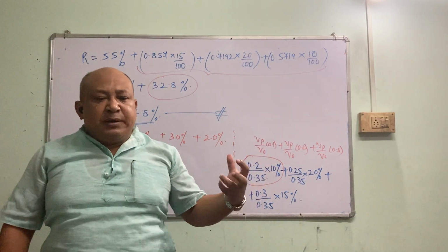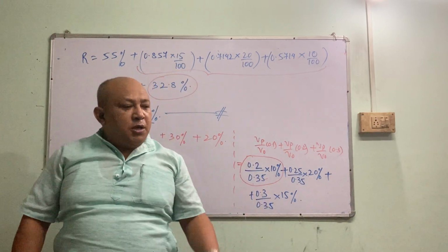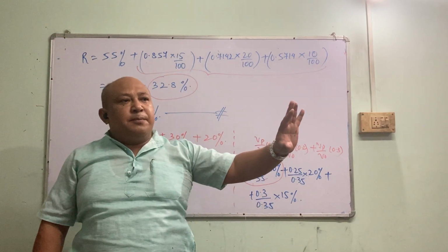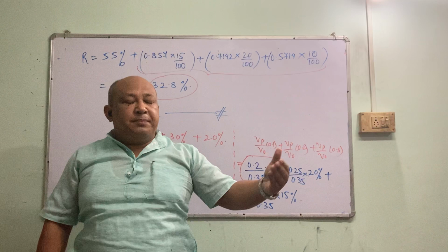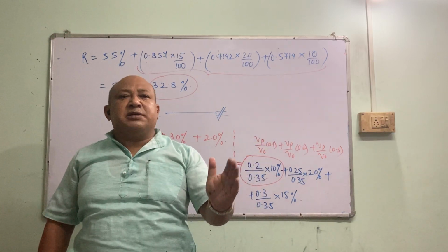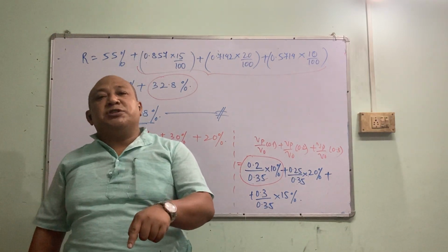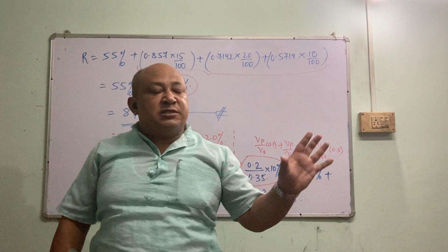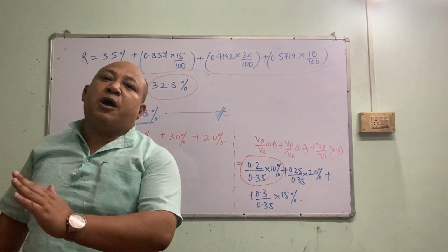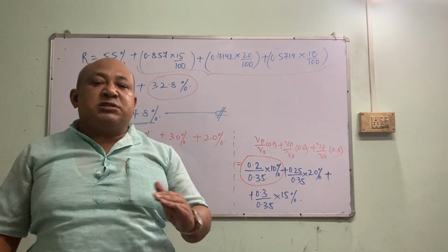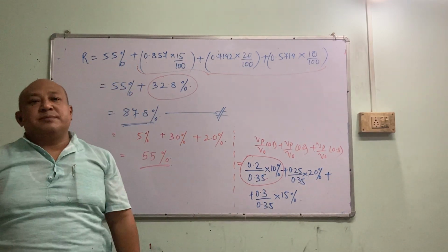On a particular rainy day, when there is a lot of rain, you collect the samples because it will contain a lot of surface runoff and sediments. You collect the sediments, you put them in the particle size analyzer, maybe in the chemistry or physics lab, and see the distribution of the particles. And then you can estimate, with the desired settling velocity and the different sizes of particles on a rainy day, how much sediment will be removed in a grit chamber and how much will escape out. So performance won't be consistent all the time, it will fluctuate. But our target will always be around 70 to 90%.